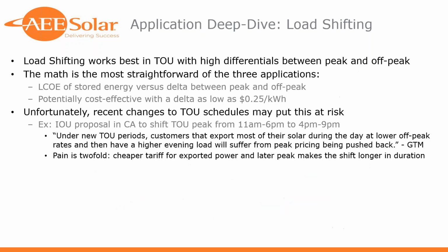Keep moving here. Load shifting. Load shifting works best in time of use areas with high differentials between peak and off peak. Think of this as energy arbitrage.